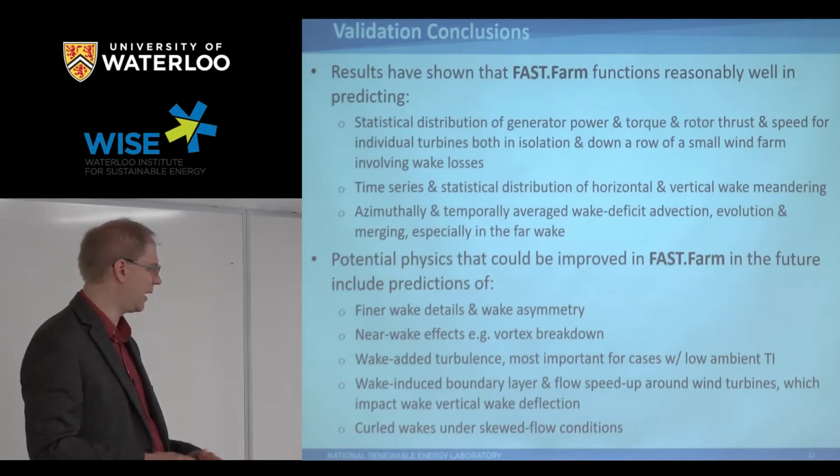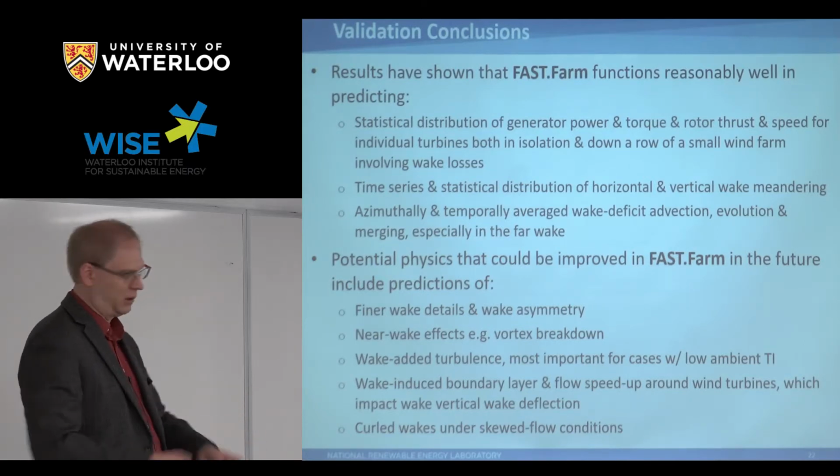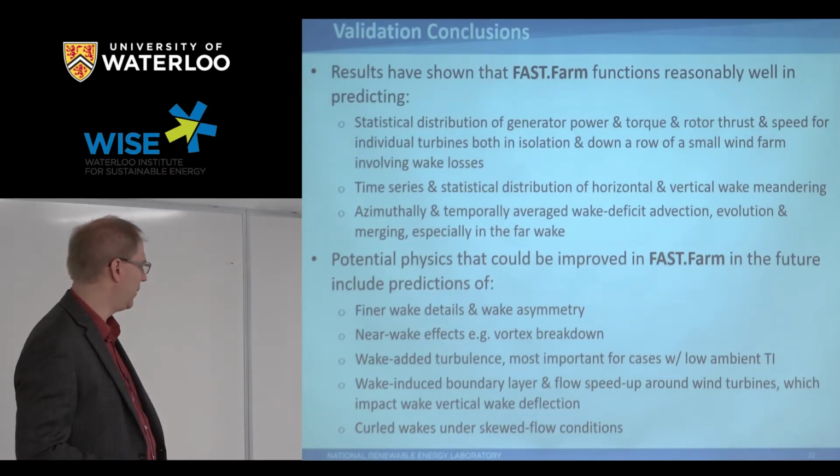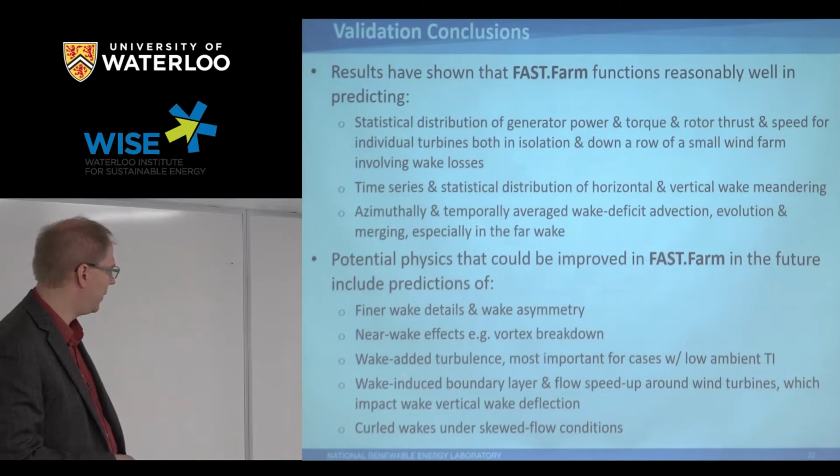The other thing we're not capturing, we capture the deficit very well, but things happen in a full wind farm, like I mentioned, the flow either going over the top or around the sides of the wind farm where flow tends to speed up. That part we're completely missing in our code, and we have to address sometime in the future.